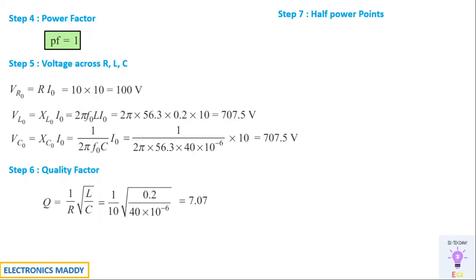So what is half power points? It is basically the lower cutoff frequency and upper cutoff frequency. Why it is called as half power points? With respect to definition of bandwidth, I told the bandwidth is defined with respect to the amount of power transferred, at least greater than half of the power that is to be transferred at a particular point in time. So that is always associated with half of the greater power. As a result, it's written as half power points. It can be twisted in this particular fashion. In order to determine the cutoff frequencies, they can ask you as half power points.